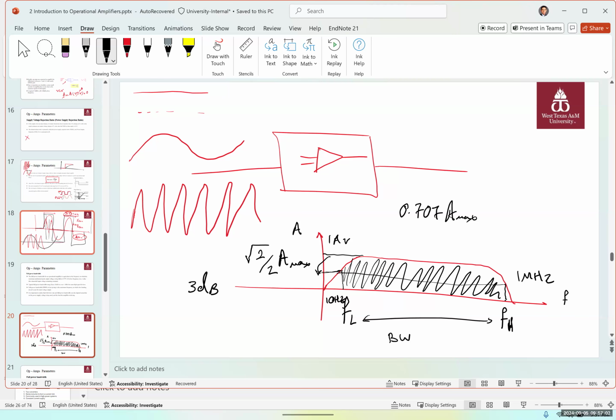So you may ask what happens, for example, in a lower cutoff frequency. If you have a capacitor which is connected to an op amp, and this is connected to the ground, and this is connected to the input. If I give it a frequency, imagine for example 50 hertz, that frequency is going to easily pass the capacitor and reach, so you're going to have no problem. But what happens if I give a DC signal to this.